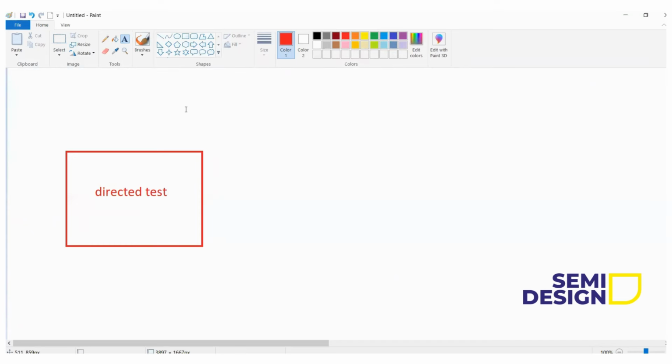Okay, say in between the project, whoever was writing the test cases, he left. Some new person came. So now what does he have to do? He has to again go through the specification because all the test cases are written directly. He has to again go to the specification, study those things and write the test cases. So it is time consuming. A directed test case can give you a correct result whether you are properly verifying your environment or not, but it is time taking, right? You have to individually check it and write it.